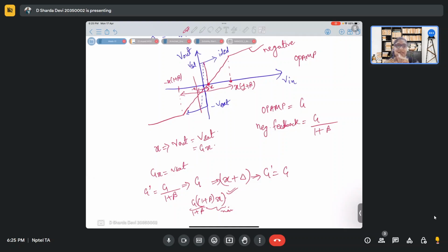That's one thing. Secondly, you will be able to give a large range of inputs and get a large range of outputs, and your amplifier will work just fine. It will not go into saturation, so you can clearly get your amplification property out of your op-amp. That's why we go for negative feedback in amplifiers: to improve them and to improve their range of inputs. It also changes properties like input resistance and output resistance.